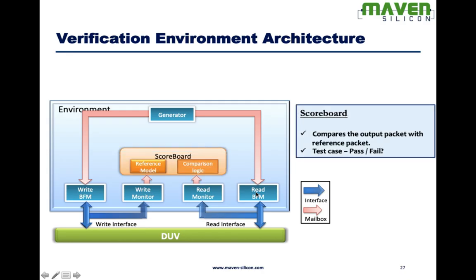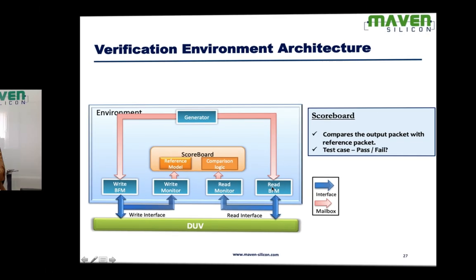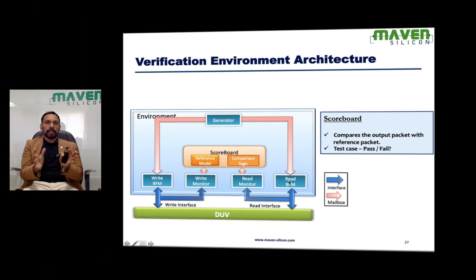And the monitors will be connected with the scoreboard. What is scoreboard? Scoreboard is the test bench component which compares the data. So here, the scoreboard compares the output packet with a reference packet.